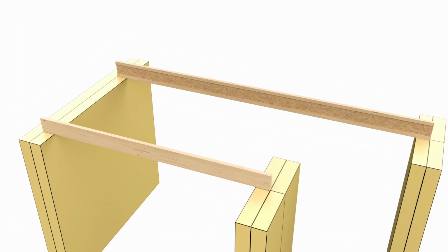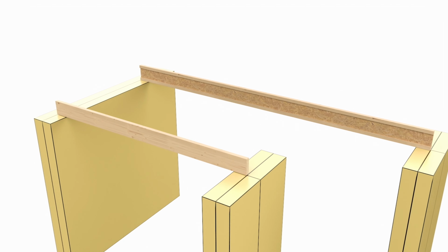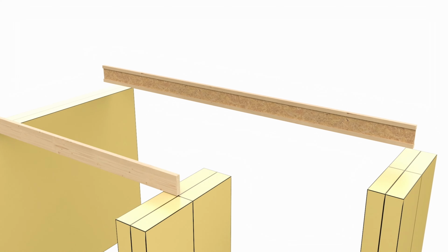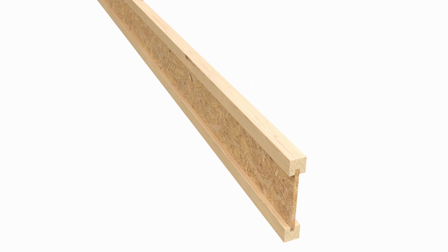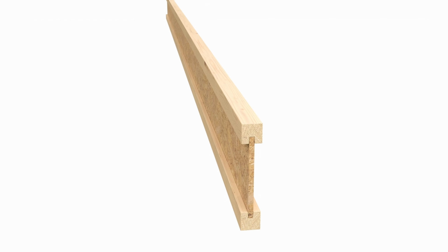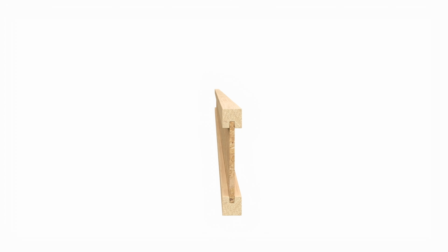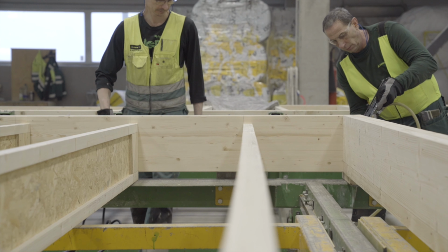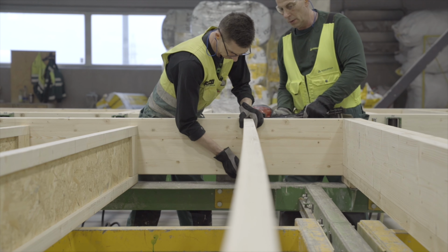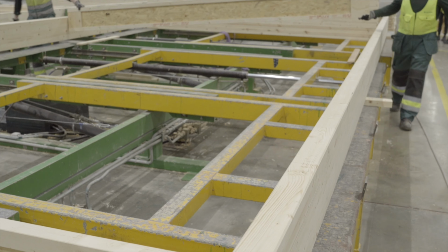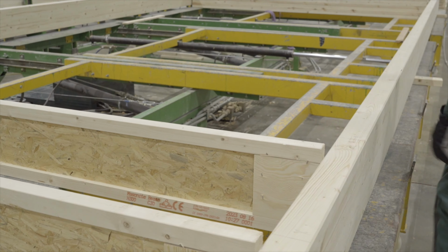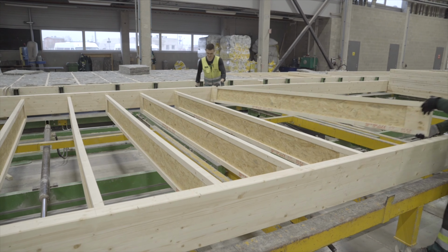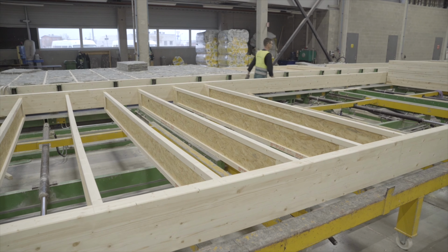I-beams can span longer distances than traditional solid wood joists without requiring intermediate supports. This allows for more open floor plans and reduces the need for load-bearing walls and columns. I-beams are manufactured to precise specifications, ensuring consistency and uniformity in construction. This helps maintain level and stable floors, reducing the chances of uneven or squeaky floors. For constructing a floor structure with I-beams, the house manufacturer's work instructions must be in precise accordance with the beam manufacturer's guidelines and requirements. Using such beams involves many specifics, especially in making joints and drilling openings.